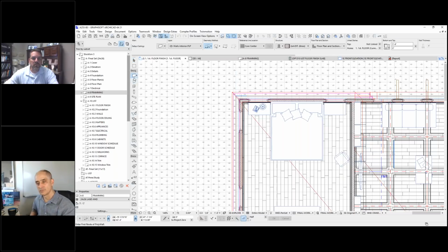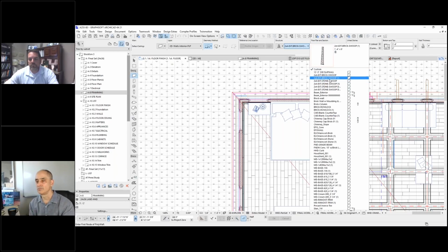the wall tool, let me go here, and I have these all set up. Our swoop walls, but our rowlock is here. And generally I'll create the rowlock as small as possible. So therefore, when I stretch it, it'll stretch to maximum amounts. Because sometimes under the window sills and things like that, you may have to scrunch it down to fit it. So I want to make sure I can fit it out. And then this becomes more usable across each project that we go through. Okay, I see 2 brick rowlocks, one with the number 1 after it, or is that just because of